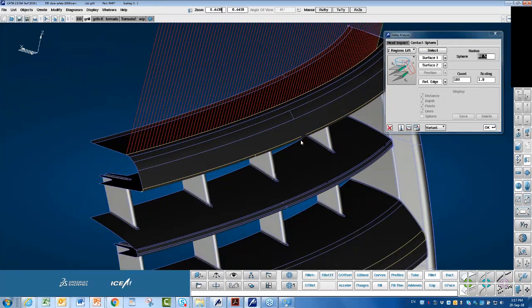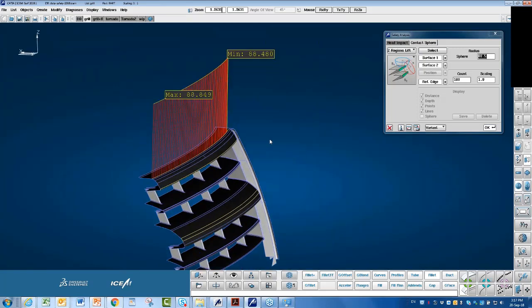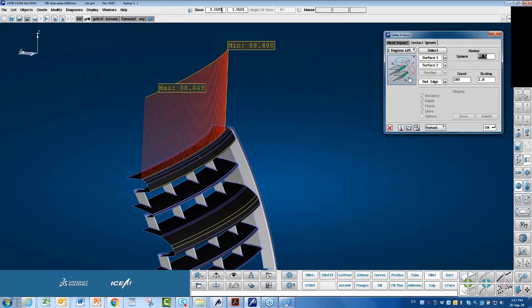There we go. Now, what this number represents here is the H value on the icon. Okay, so there's a rolling sphere like before running between these two fillets in this direction. But then using the reference edge, there's a second sphere rolling across the top.